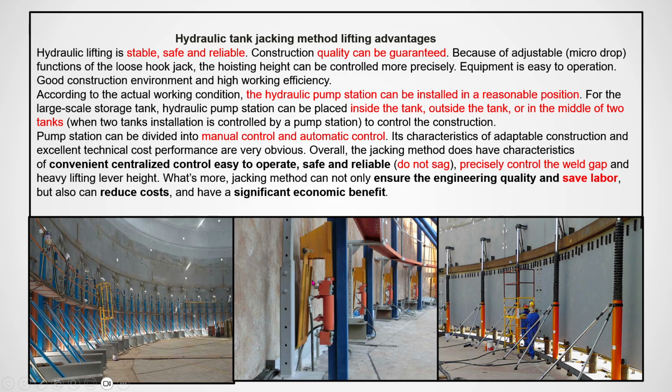With the help of this jack, you can maintain the clearances and do the welding. You will see a lot of jacks are there, and you can put the pump house at the total center position, inside. It is remote controlled, and you can keep it outside also. With the hose you are lifting these jacks, and precise control is possible. Such a big tank is only possible with the help of the jacking process.